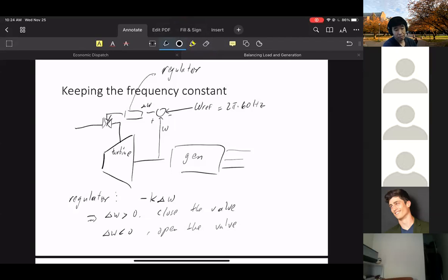For the demand, we don't know the voltage and the angle. So when we build the Jacobian matrix, do we still need to calculate from P1? We don't have to do P1 because bus 1 is the slack bus. We have to do P2 to P12 and Q2 to Q12.